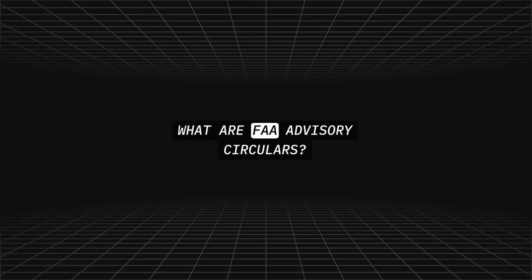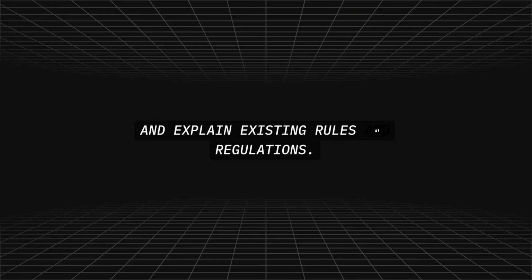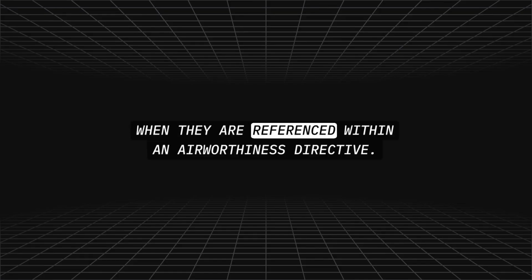What are FAA advisory circulars? They are non-regulatory FAA publications that expand upon and explain existing rules and regulations. When are service bulletins considered mandatory? When they are referenced within an airworthiness directive.